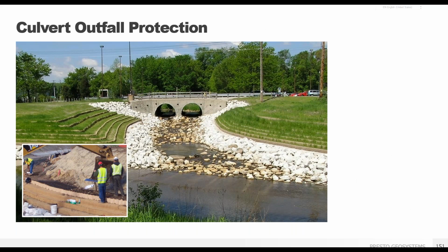If you want a vegetated channel but have strong flows, a pro tip is to include surface protection over the panels, such as a TRM or core fabric, as you see here. This is intended for short duration events rather than continuous high flow.